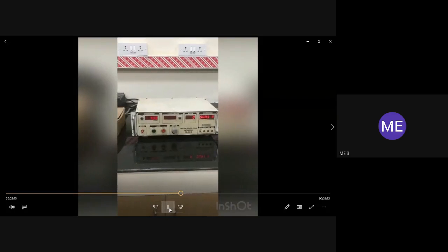Same procedure: time 3 minutes, speed 500 constant, load 4 kg. Again the stopper will be fixed. Again the specimen will be fixed. And the same set of experiment is conducted for different loading conditions. Not much difference. You will remove the stopper.